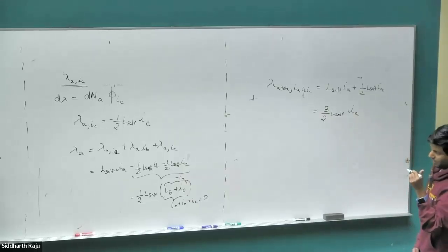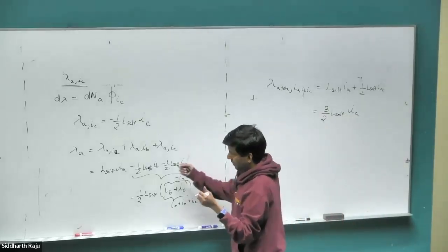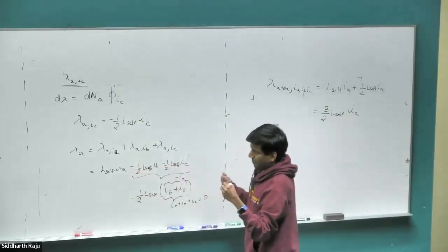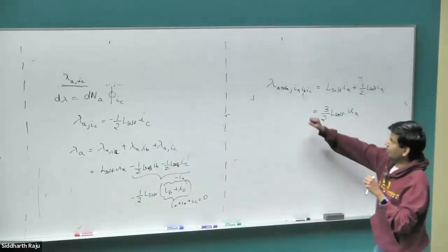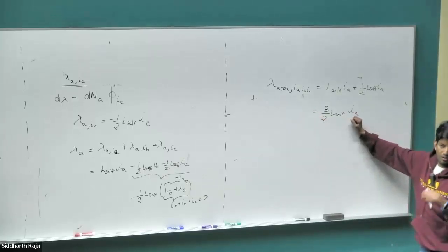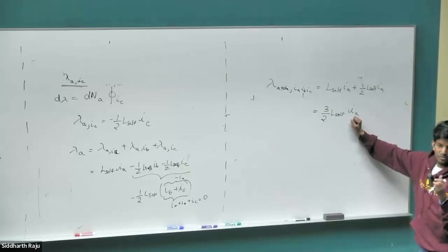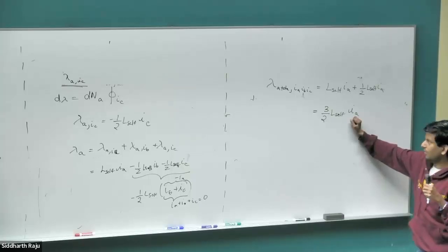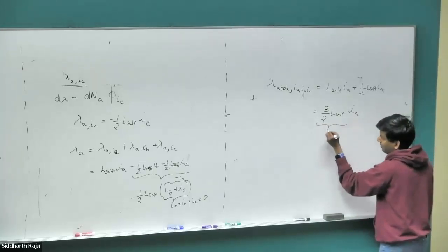You have three different currents. Of course, the three of them are not independent. One of them is dependent on the other two. So you have two independent currents, and with the sum of the inductances, the net flux linking the coil is purely a function of one of the currents alone. The information gets folded in somehow because the other two phases are in reality dependent on one another. Because if I tell you one of the currents and its frequency and phase, you can figure out the other two currents, because in a three-phase system that is predetermined. So this is what our net inductance is going to be.